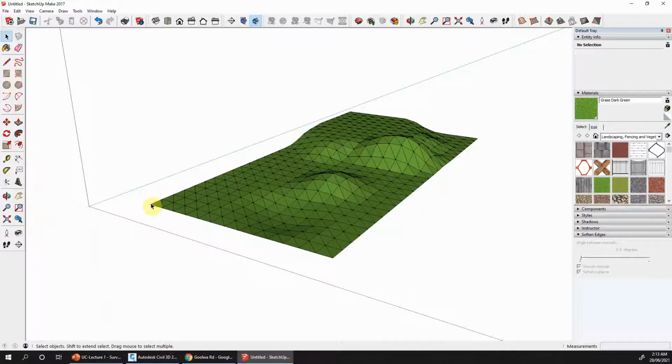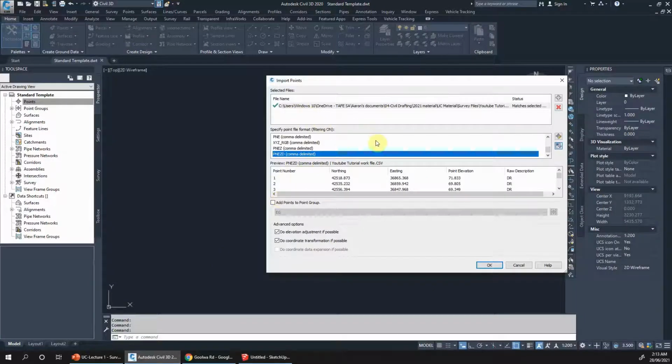In other words, we call them easting, northing, Z component. So if you look here, I'm entering these points currently. I've got those from the surveyor, the guy who was on site measuring these points and giving me the data. And I'm entering them as the point, north, east, Z, which is the height, and description.